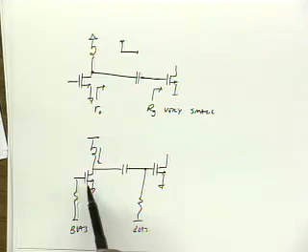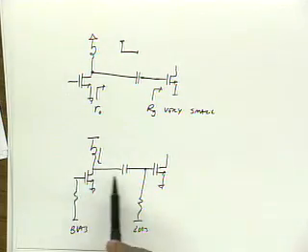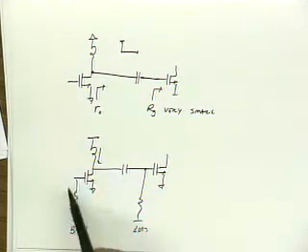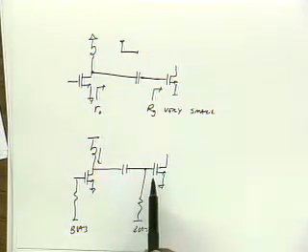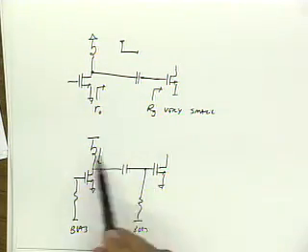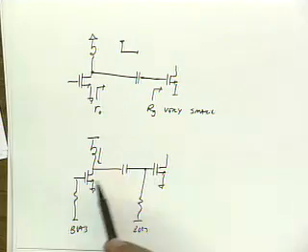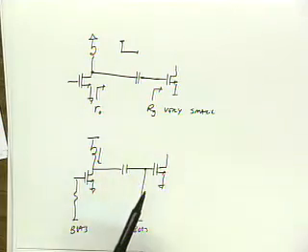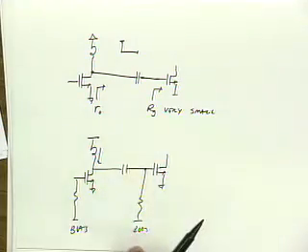The downside, though, is what if we wanted to low-pass filter the output of this stage before it drives the second stage? This is doing the opposite. It's high-pass filtering. In that case, we would use the other termination, but we'd end up having to put in a lot of extra elements.